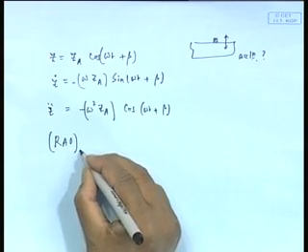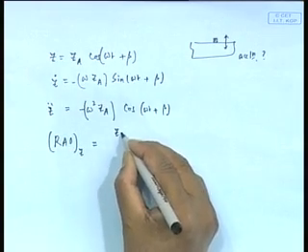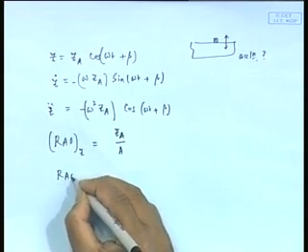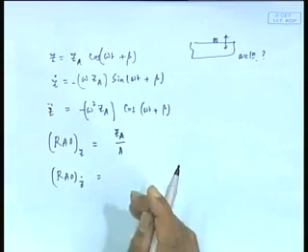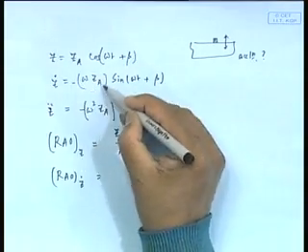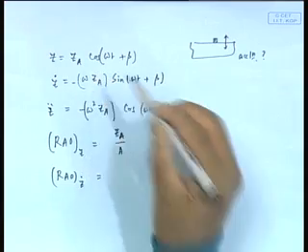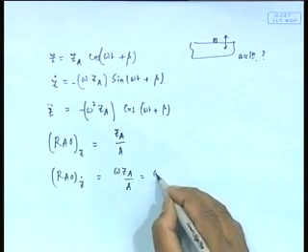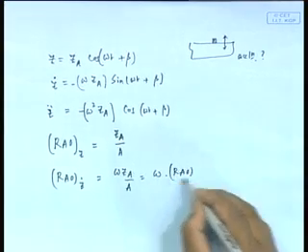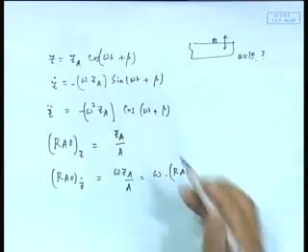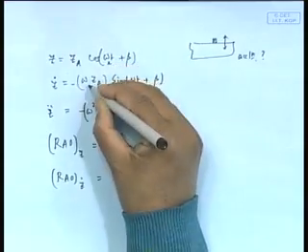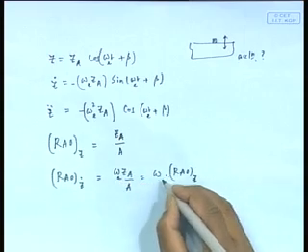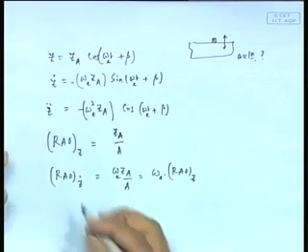I am writing this as RAO for Z is amplitude by A. Okay. What is my RAO for Z dot? How much is the amplitude of that? It is omega Z A, right. So, it is omega Z A by A. Well, of course, we should probably put omega E here. Agree?